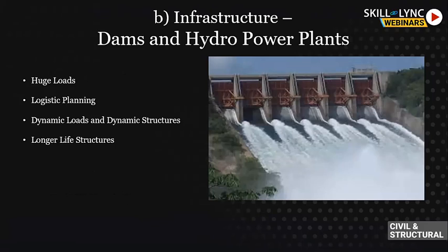One part I did not speak about in this presentation is the life of a structure. A residential building is typically 50 years, but for commercial buildings or where the population is higher, like hospitals, dams, and power plants, it goes from 50 to 100 to sometimes 500 years of life. So you have to design structures for different lives also. Dams are one such example. You would see dams from the British era still standing because they were designed that way.